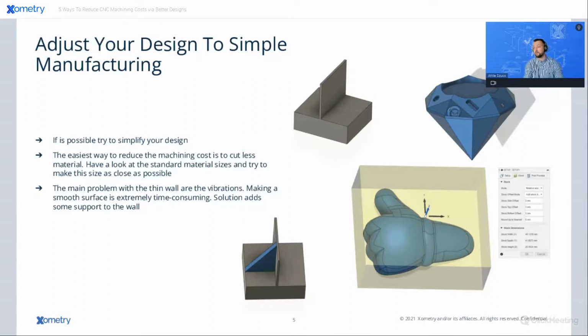They could easily be bent, and it also reduces tool life. So what could be a solution? Adding a massive radius on the bottom, and you can also add a support wherever you can, because that support makes it significantly stronger and reduces the chance of vibration, which is obviously one of the biggest enemies on a CNC.